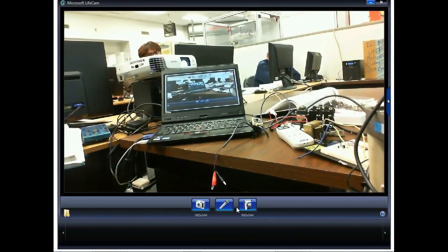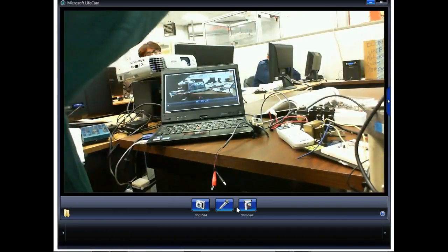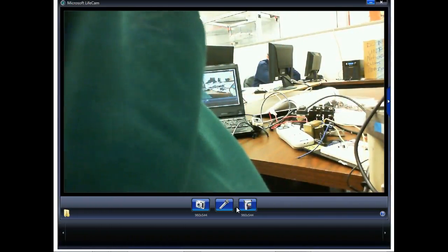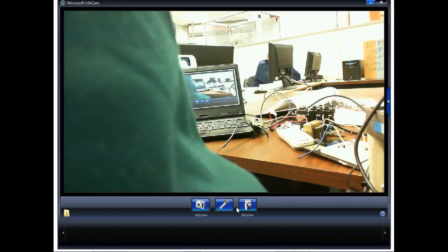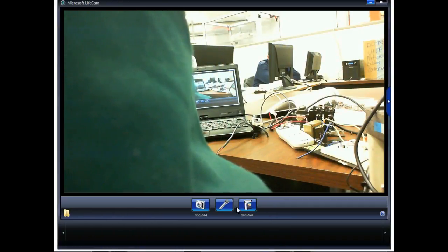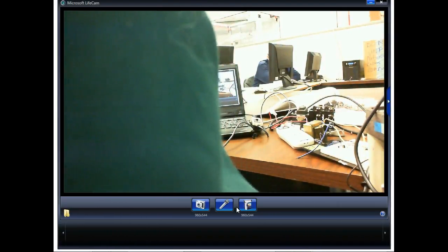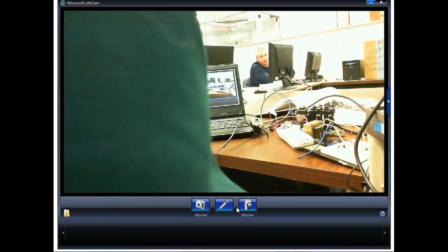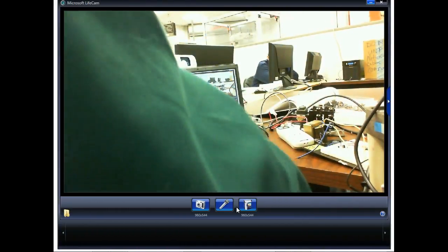Or you might have to get a device called a logic analyzer. I'll pull that thing out and show you that. The problem with these: how many signals can I look at with this at any one time? What if I'm trying to see all highs to get a low, and I've got a 30 input AND gate, or a 16 input AND gate? Well, a scope's not going to do any good because I can only look at two things at the same time. So we'll show y'all a logic analyzer, which gives us the ability. We've got some that can look at 32 input signals at the same time,